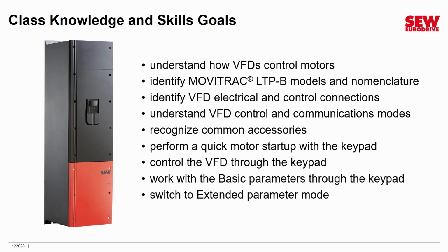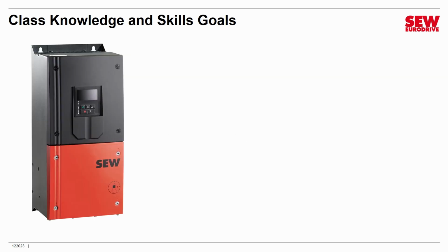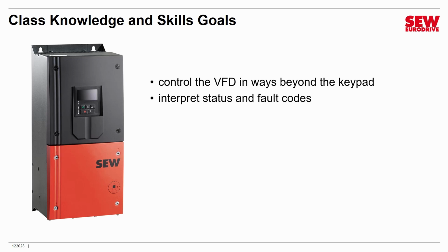And then you'll learn how to switch to extended parameter mode, where you'll gain much additional functionality through an extended set of parameters. We'll then move into some more intermediate skills by learning how to control the VFD in ways beyond the built-in keypad, such as terminal control mode. You'll learn to interpret status and fault codes and to deal with problems when they come up.